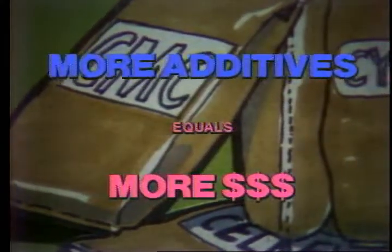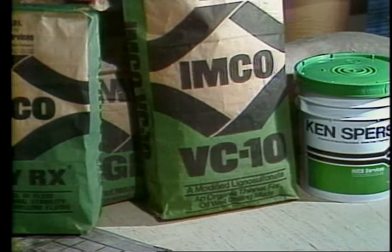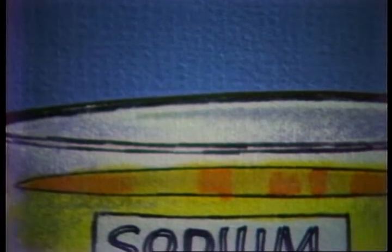One thing to keep in mind, though, the more additives you put in your mud, the more expensive it's going to get. It's not uncommon to have $500,000 tied up in the mud system and additives alone. So the one thing we definitely want to do is keep it as simple as we can. We're going to get into these additives in more detail in a little while. But let's take a look at one particular contaminant right now, and that's soluble salts.